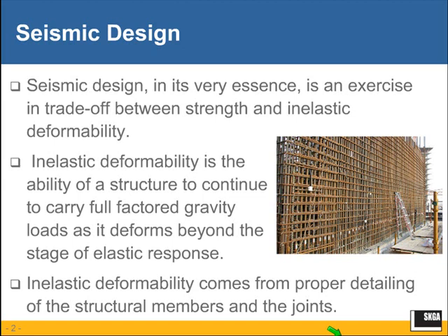Seismic design, in its very essence, is an exercise in trade-off between strength and inelastic deformability. Inelastic deformability, in a very general sense, is the ability of a structure to continue to carry full factored gravity loads as it deforms beyond the stage of elastic response. Elastic response means that when the earthquake passes, we get our structure back intact. There are no residual displacements and therefore no damage associated with elastic response.